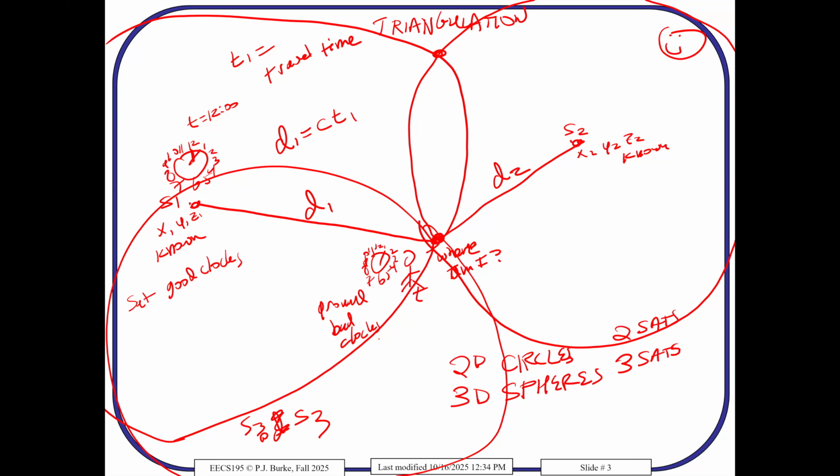The energy level difference between two states in some atoms is around 10 gigahertz. So you have a really nice 10 gigahertz source if you can phase lock an oscillator to the atomic energy level transition. And you can get nanosecond or better timing on that, which is good enough for GPS. It's much better than a nanosecond. The satellites do have lasers on board, but we only have 20 satellites, so we can afford 20 lasers.